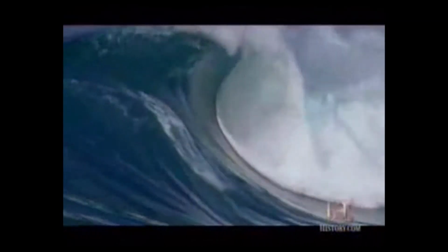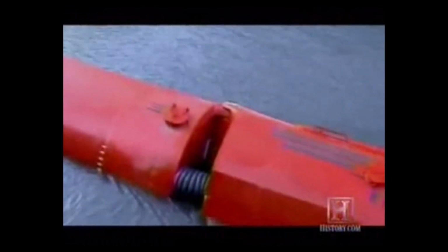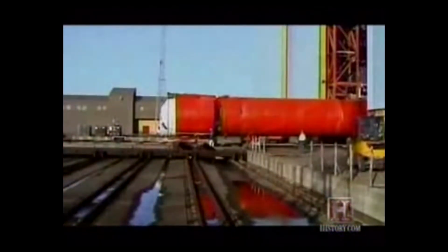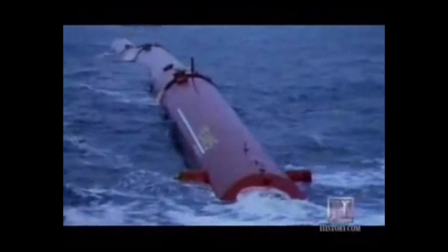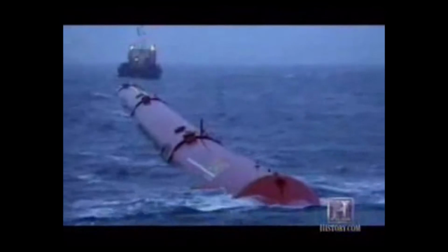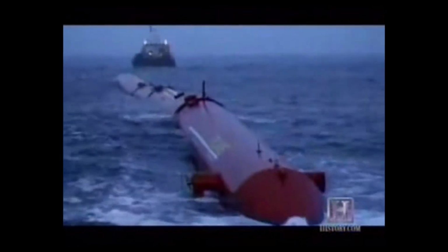Wave power is an even newer technology. Yet it may hold the most promise of all, since wave power can be captured anywhere on the ocean. In this design, a 450-foot chain of pipes, connected by hinged joints, sits semi-submerged on the ocean. Each motion of the waves is resisted by hydraulic rams located in the hinges. This action pumps high-pressure oil through hydraulic motors, which drive electrical generators. Electrical transmission lines also keep the floating power plant tethered to the ocean floor.